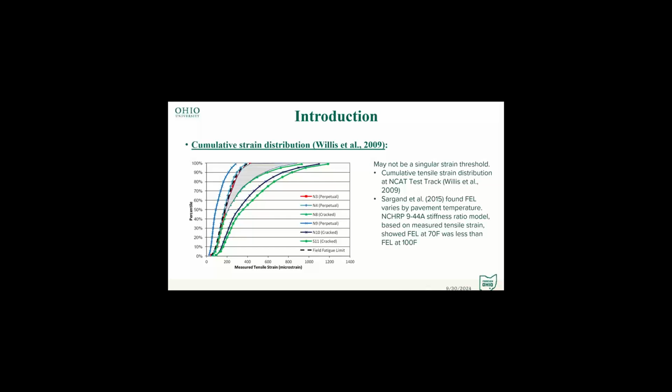The way that we looked at the strain measurements is we were comparing them back to our cumulative strain distribution that we used in design. I also did some work taking those strain measurements that were made in the field and extrapolating them based on the temperature strain relationships that I could develop from the measurements that we did have. Mind you, the conditions under which we tested weren't reflective of the extreme temperatures. As Sam mentioned, we did have some cover that prevented getting some of those extreme temperatures in the measured data. So I extrapolated out and compared it back to those sections that we knew behaved perpetually on those other cross sections in Ohio, namely the APLF, the thinnest, the 10-inch cross section that was highly modified HPM material all throughout in the APLF.